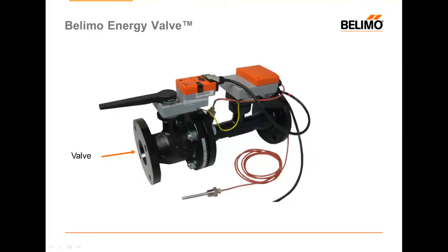Let's take a look at what goes into this product. Let's start from simplest and move to the more complex. Up front we have a standard control valve. This is a typical characterized ball valve up front. Sitting on top of that is an actuator. This is probably the most technologically advanced actuator ever produced, but at the end of the day, you give it a 0 to 10 volt signal and it rotates 90 degrees, so it's an actuator.